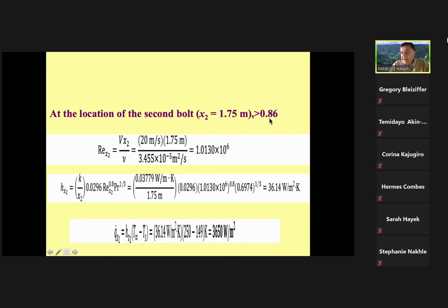Okay, look at here. The case here is after 80 centimeter it becomes turbulent. Therefore, it means the first 80 centimeter is laminar. The next one is turbulent. Therefore, both of them have probably equal contribution. In that case, if I was going to use it, I would use the last equation that considers the laminar contribution plus the turbulent contribution. Okay, perfect.